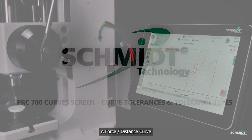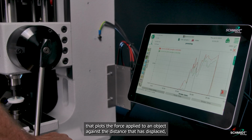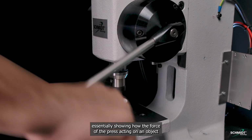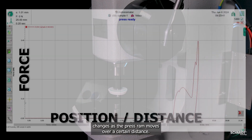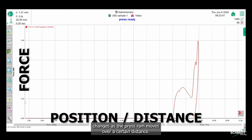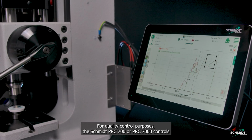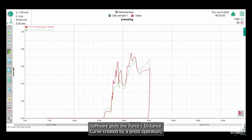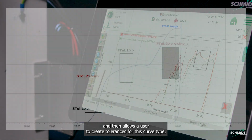A force distance curve is a graphical representation that plots the force applied to an object against the distance that it has displaced, essentially showing how the force of the press acting on an object changes as the press ram moves over a certain distance. For quality control purposes, the SCHMIDT PRC700 or PRC7000 controls software plots the force distance curve created by a press operation and then allows a user to create tolerances for this curve type.